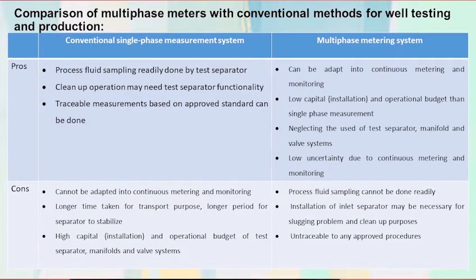And for the disadvantages, sampling of the process fluid is not readily available. An inlet separator may be required as a slug catcher and for well cleaning purposes. And multi-phase metering is not traceable to any accepted standard.